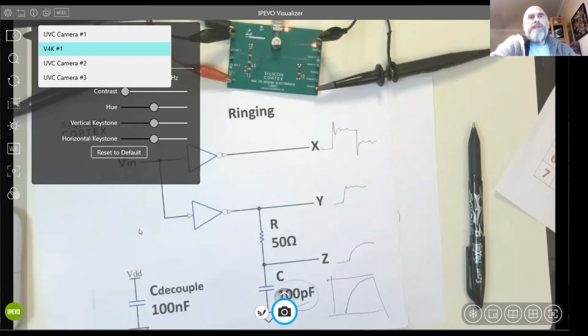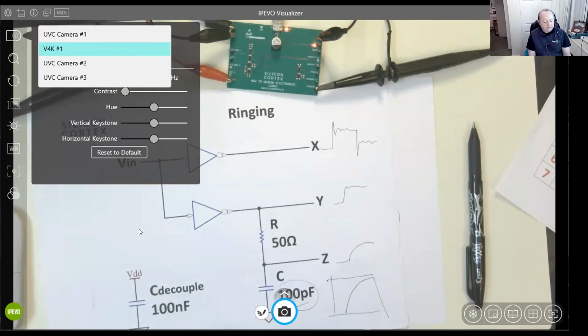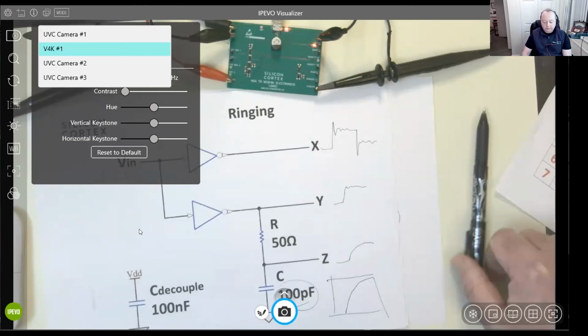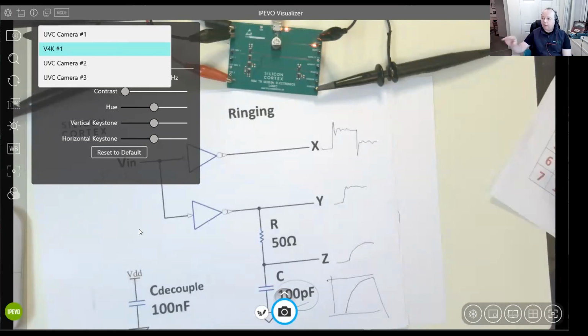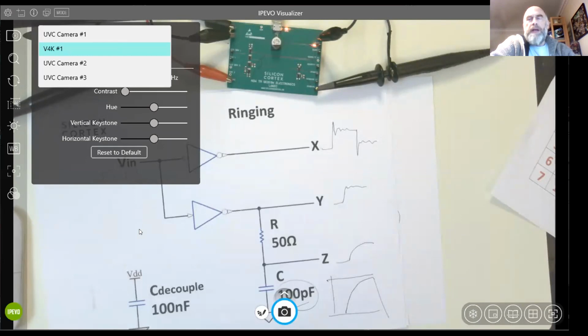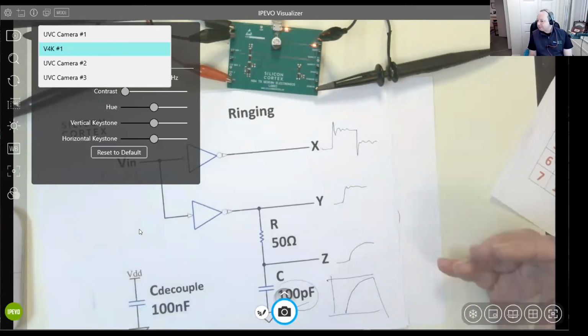And when you were saying it's an onboard type of connection, would using it on a Raspberry Pi hat, the board which actually fits on top of the Pi, be fine? Oh, that's fine, you're going there for a short connector. You just don't want to run I2C or SPI over long cables, they're not designed for that. Within an enclosure would probably be fine. But don't forget, cables are the undoing of every product.